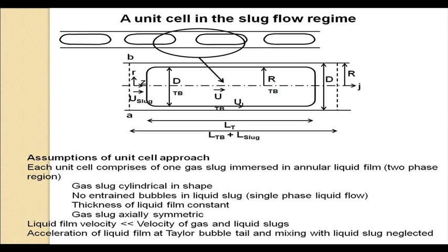the annular flow. So, therefore, the other assumption which we make here is that the thickness of the liquid film is constant, which is quite a logical assumption, because the thickness of the liquid film becomes asymmetric. It is usually wider in the lower portion as compared to the upper portion, and this occurs primarily due to the effect of gravity.